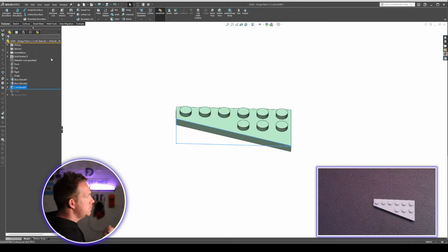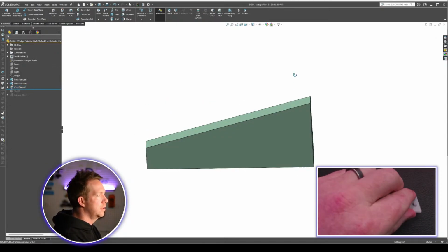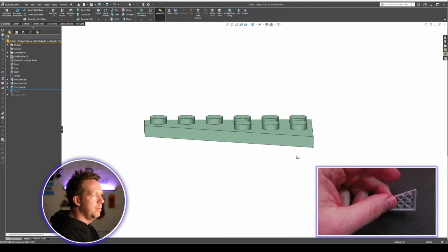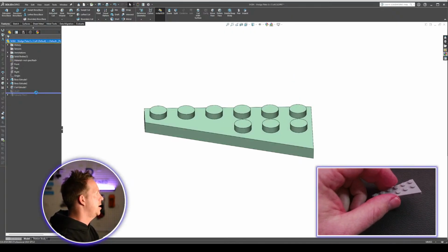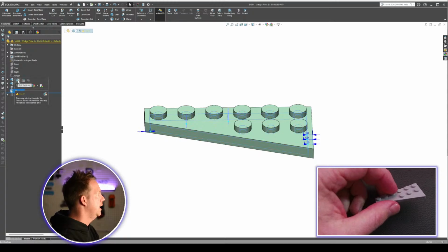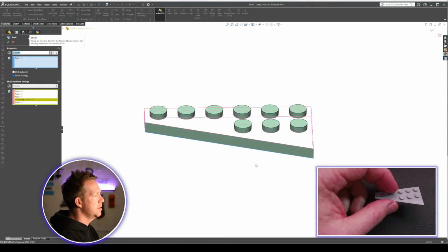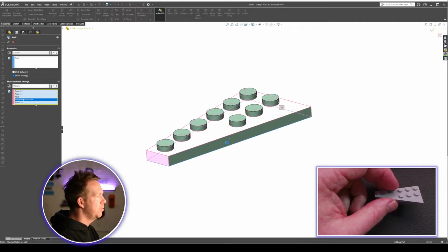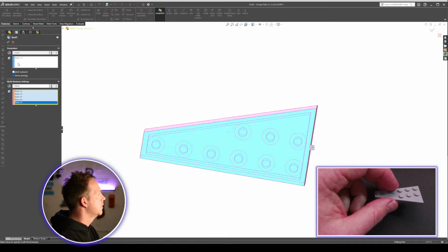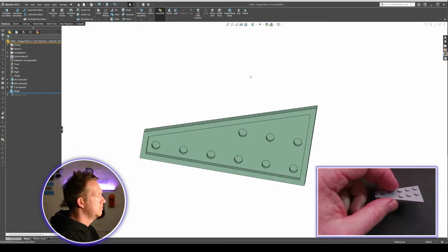All right, so that's got my wedge shape now. But when I roll down the shell, I had a custom wall thickness for one of the sides. So you can see it's missing face at a 1.5 thickness. So I've just got to replace that, press the tick here, press OK.